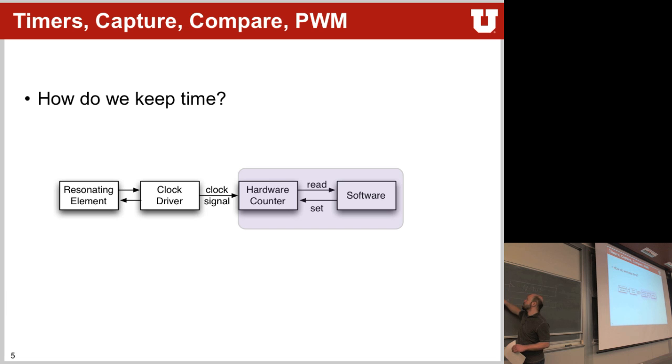So there will be some logic in here that will make sure that you capture an actual value, not while it is incrementing. Oftentimes it's called a synchronization block, and there are lots of different techniques of dealing with this metastability so that it does not happen. Any questions to that? Okay. What's the problem with these things then? Assume you have a block here that makes sure that this will never be metastable. What could be the problem?